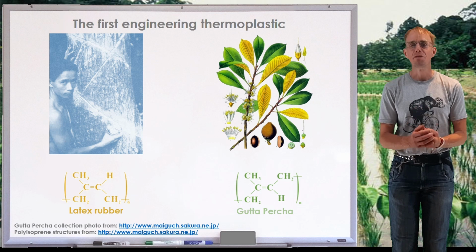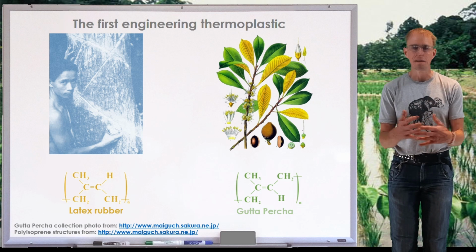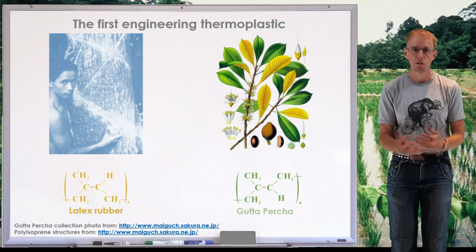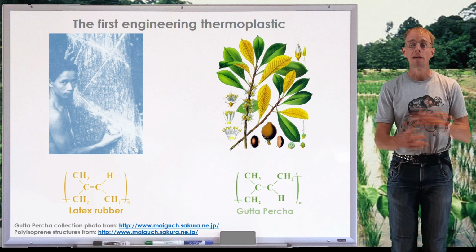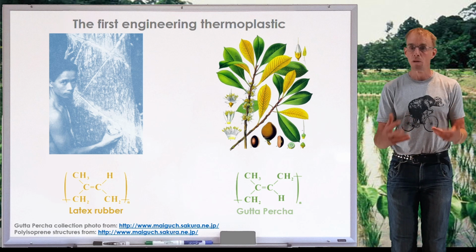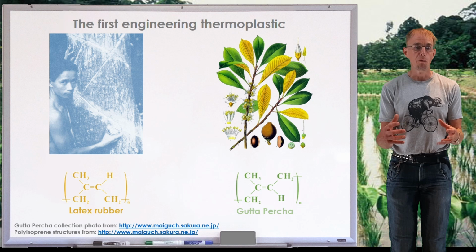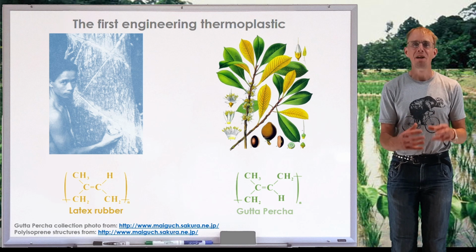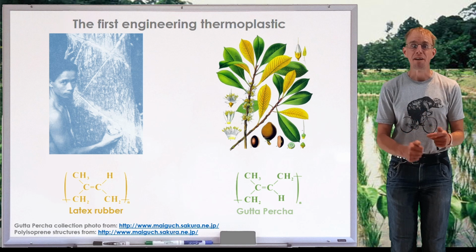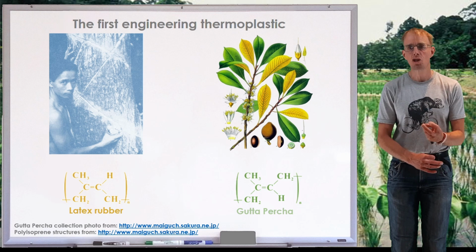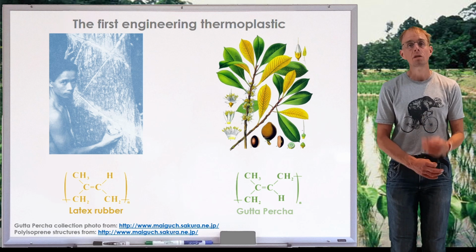And that remarkable difference is that gutta-percha, once it's been collected, and that's by means of processing and crushing the leaves and then extracting the polymeric product from those crushed leaves, and then taking that polymeric product through a number of purification stages until you end up with basically a set block of trans polyisoprene. Now, that set block of trans polyisoprene will effectively soften at around 60 degrees C, and so it's thermoplastic. And so gutta-percha represents, in effect, the world's first engineering thermoplastic.